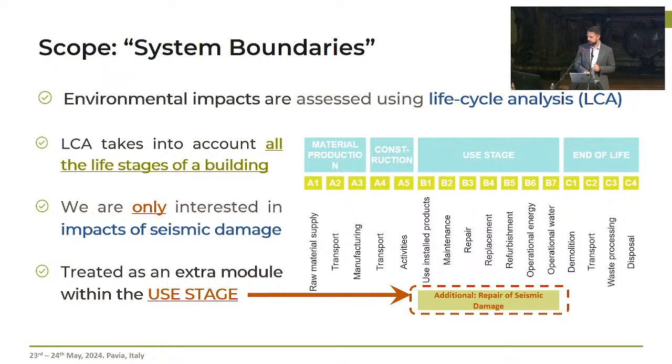Now, you mentioned something very interesting, which is the effect of other factors like transportation. Yes, it's important, but when we refer to the data of embodied carbon, most of the manufacturers are just considering A1, A2, and A3 because it's the most significant part. Think of transport, we can include it. There are simplified factors that depend on the type of the vans that carry the materials.